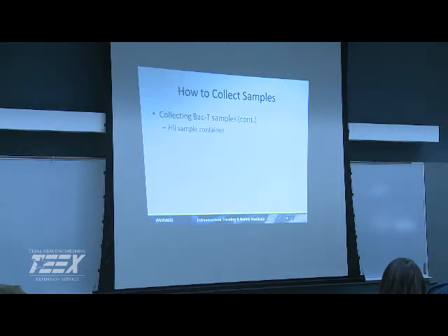So yeah, there's different types of preservatives, right? When you're pulling lead and copper, you need to have an acid in there to lower the pH so it stays in solution. So there's different preservatives that you're going to have in your bottles. You don't want to rinse that out. And especially sodium thiosulfate is a very important dechlorinator, so we don't want to rinse it out. But it's interesting some of the responses you get.